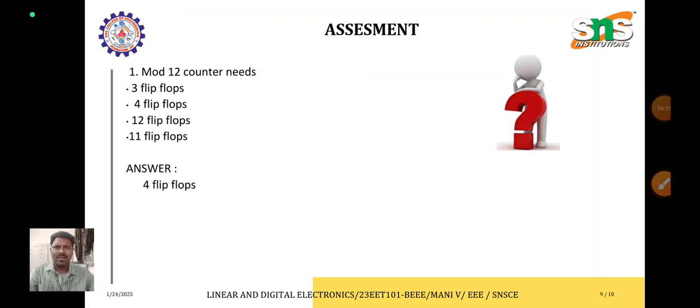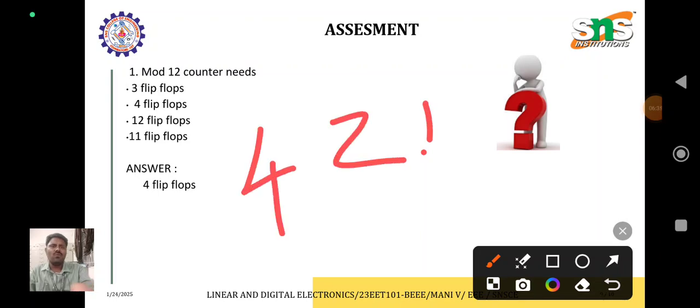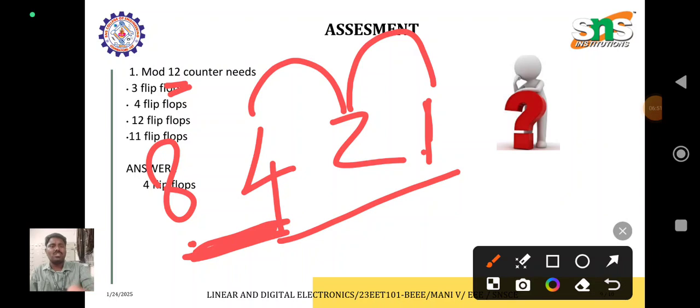And this is an assessment. A mode 12 counter needs how many flip-flops: 3, 4, 12 or 11? The answer is 4 flip-flops, because the flip-flops are based on 1, 2, 4 and 8. If you use 3 flip-flops, the possible count is 4 plus 2 is 6, plus 1 is 7. You get only 7, but here we need 12. 8 plus 4 is 12, plus 2 is 14, plus 1 is 15. Above 7 and up to 15 you can use 4 flip-flops.